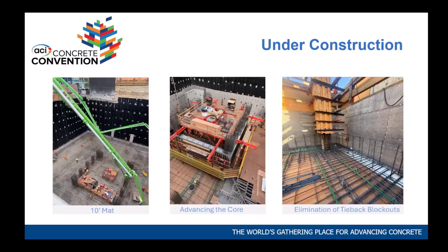And what they do is they come back later when the tower is up to level 2, they come back and shoot the basement walls with shotcrete. And they're pretty thick basement walls, 16 inches.